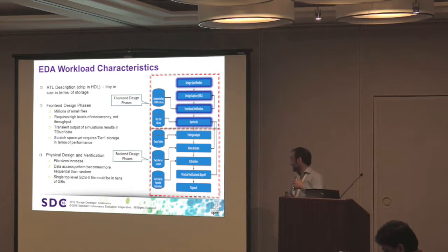In the earlier days, like in the 90s, this wasn't as big of a deal, but as the chips got smaller and smaller to nanometer geometries, even the wiring in between the blocks matters, and the resistance or the capacitance that it may induce could have an ill effect on your overall intended results, right, or expected results. So there is a workflow known as extraction or parasitic extraction. You then do physical verification and sign off, and then you eventually tape out the chip to the foundry, right?